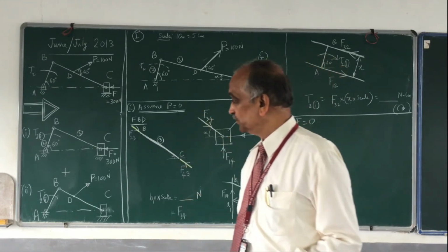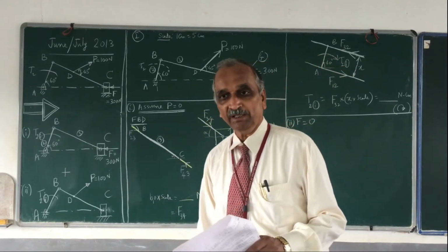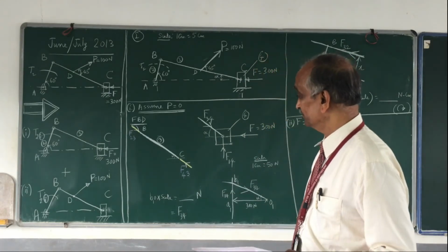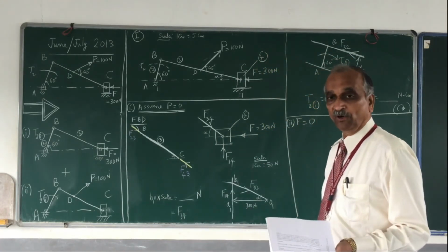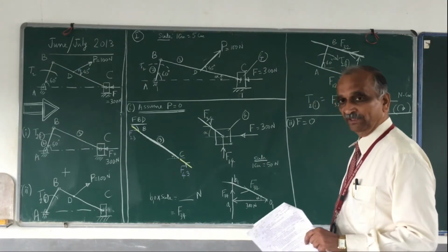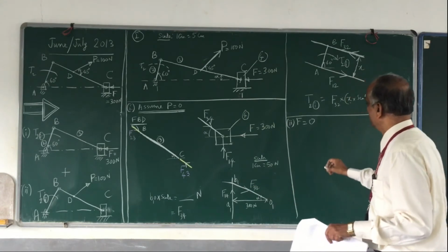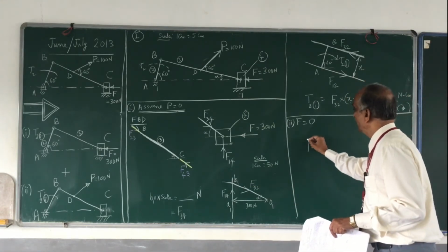In addition to this, you also have a force P which is at point D. Therefore, it is a 3-force system. Now coming to link number 4, I don't have F. Therefore, link number 4 is subjected to only 2-force system. What is that? Link number 4.